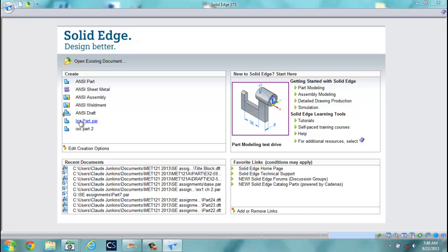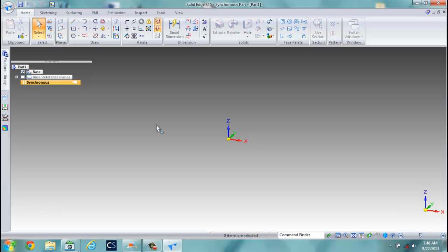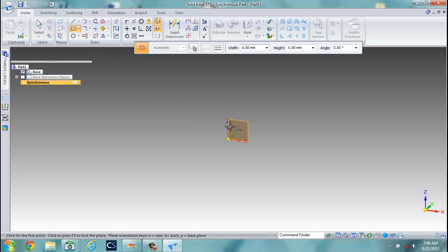And I'm going to show you a couple little tips and tricks that make it a little quicker than what we initially did in class. I don't really have the sheet to the side, so you can open your book and watch through this. I'm going to start with a rectangle by center. I'm going to go to this plane, and Control H, remember, will rotate our view. You can see this little bar shows up with a little drumstick, tells you you're right at the center point. And we're going to pull this out.